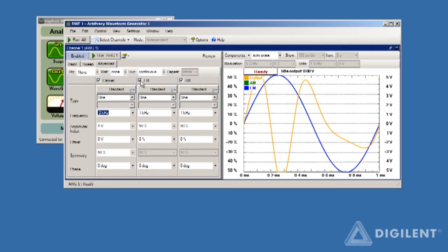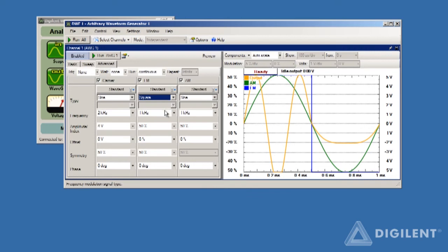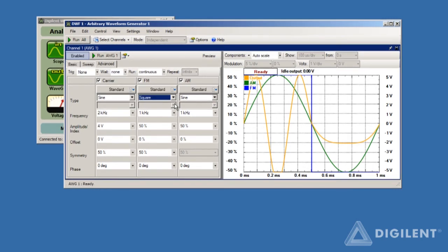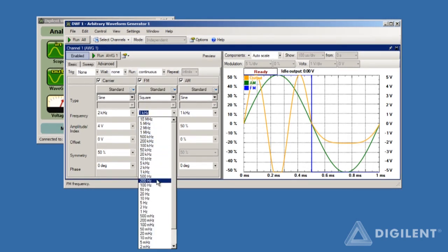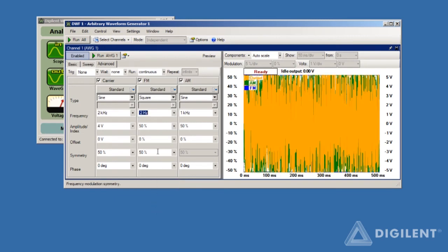As a first case, let's modulate our sine with a square wave. A square wave has only 2 levels, so we should hear a sound that switches back and forth between 2 frequencies. Let's change our frequency fairly slowly, so choose a 2 Hertz frequency for our FM signal. Now the frequency of our sound will be high for 1/4 of a second and low for 1/4 of a second. The pattern will repeat itself twice per second.